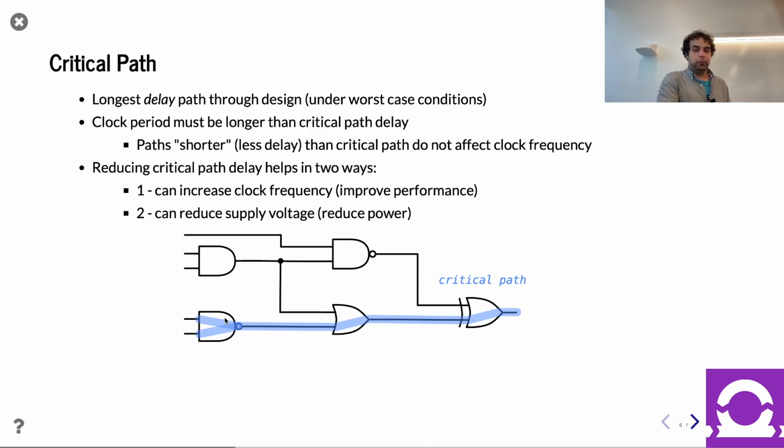They don't just have one AND gate to pull from, right? They often have multiple variants to choose from, or multiple conditions, multiple voltages, special voltages, that kind of stuff. And so they will pick to use the fastest gates they can along the critical path, but along the non-critical path, they can often get by with much slower gates. They can also perhaps, when they do placement and routing, give these things longer routes because it's not as important. They can use that slack to really try to improve the critical path, right?